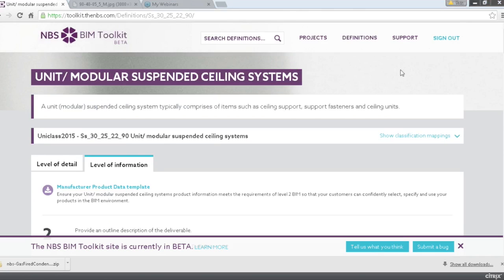Okay, then, so we've got a question about COBie. What is COBie? COBie stands for the Construction and Operation of Buildings Information Exchange, which is a bit of a mouthful. COBie in the UK is a British standard, and essentially it is a standard form to collect technical information about the products that go into a building, essentially. So you will describe a boiler or a ceiling using a list of properties that describe what it is. The manufacturer name, the manufacturer model number, the date it was installed, when the next service is due, for example, if it's a boiler, and that kind of thing. So COBie is just a basic information schema that can be viewed in Excel format.